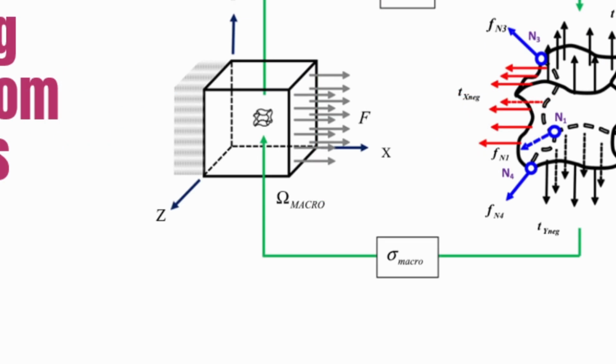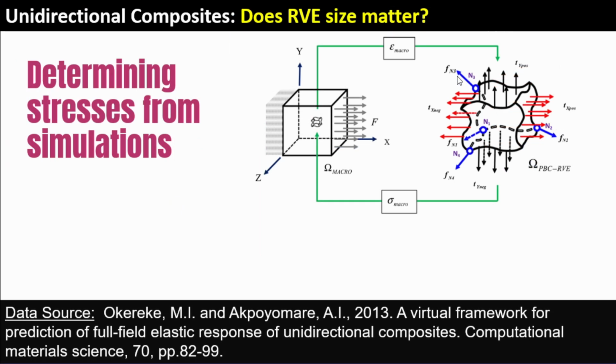So basically what we want to try to do here is that this RVE, this representative volume element that we're looking at, whether it's 2D or 3D, we are tracking the displacement of nodes in the corners. These ones in blue are the things whose displacements we're tracking: node 3, node 1, node 4, and node 2, if it's a 3-dimensional system, but clearly in this case we only have 4 nodes. So we could track all those nodes, record them in a variable, and then use them to find our stress and strain.